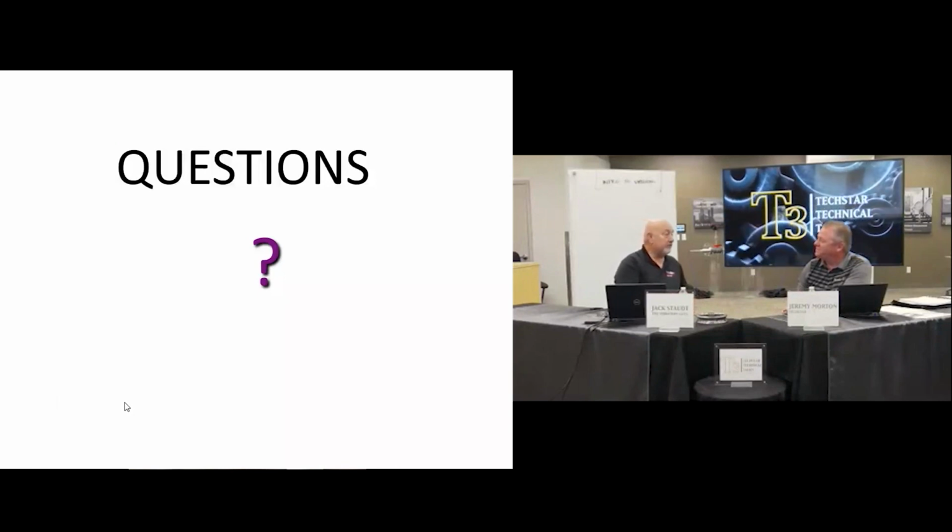The way motion amplification works is that your video has like 6 million pixels on it. Each pixel is an XY vibration transducer. So you've got 6 million XY vibration transducers, and we're measuring the motion of each pixel and then doing an average over it. You can zoom into maybe a structure issue or a piping issue, pipe strain or something like that. You can really identify that.